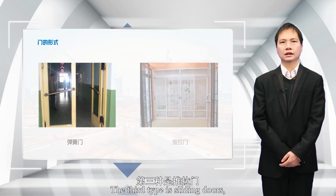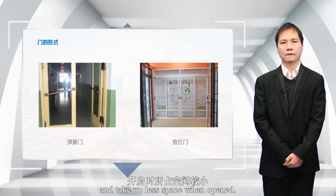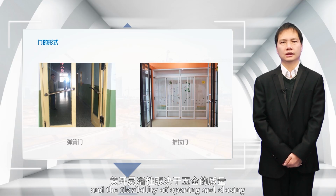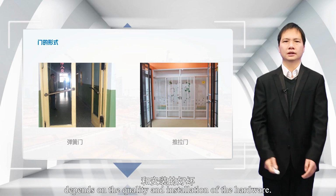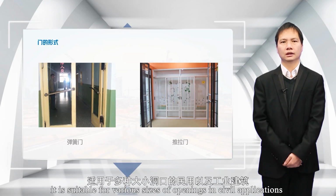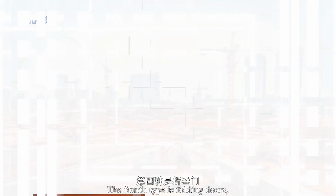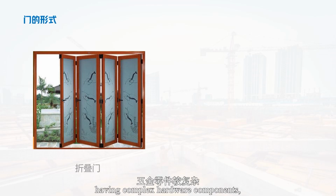requirements. The third type is sliding doors, which are easy to make, and take up less space when opened. However, the hardware components are more complex, and the flexibility of opening and closing depends on the quality and installation of the hardware. It is suitable for various sizes of openings in civil applications and industrial buildings. The fourth type is folding doors. The advantage of a folding door is that it occupies less space when opened, having complex hardware components, requiring high installation requirements, and suitable for various sizes of openings.